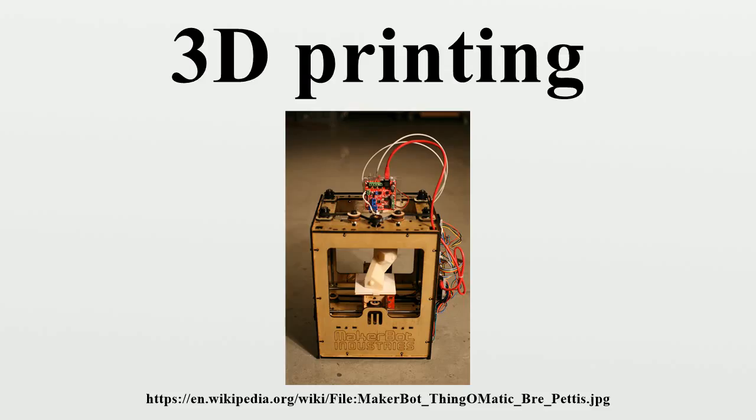3D printers give designers and concept development teams the ability to produce parts and concept models using a desktop-size printer. Finishing, though the printer-produced resolution is sufficient for many applications. Printing a slightly oversized version of the desired object in standard resolution and then removing material with a higher resolution subtractive process can achieve greater precision. Some printable polymers such as ABS allow the surface finish to be smoothed and improved using chemical vapor processes.